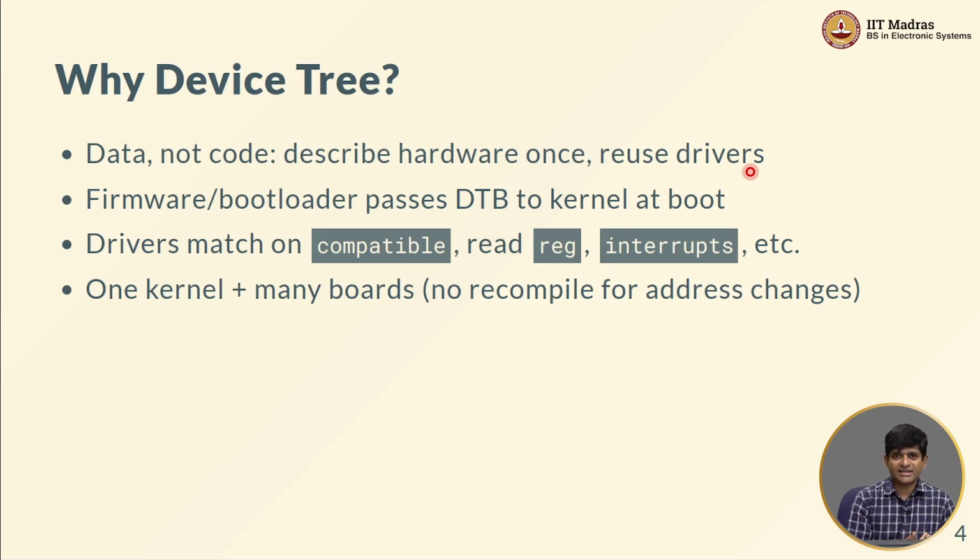But the interesting thing is, rather than going around specifying exactly what particular module is placed where, they use the data, the device tree, in order to specify how the different blocks are connected inside the Raspberry Pi. This is a text-based description of the Pi platform, which you can read and understand, and it gives you a lot of insight into how the entire system is connected.